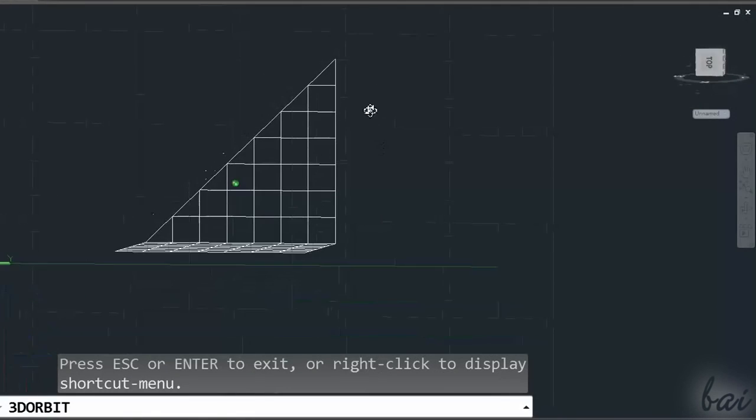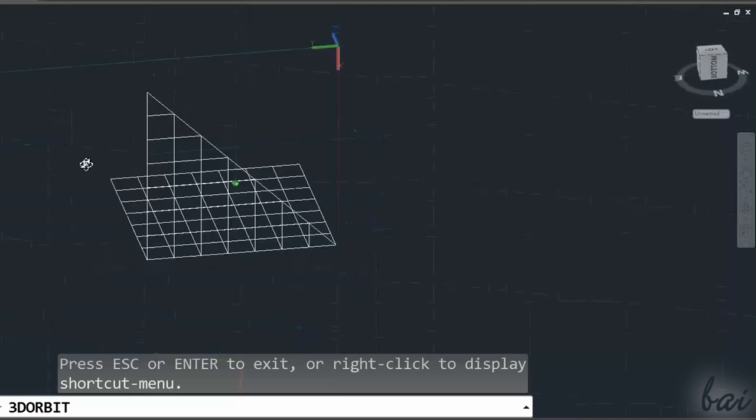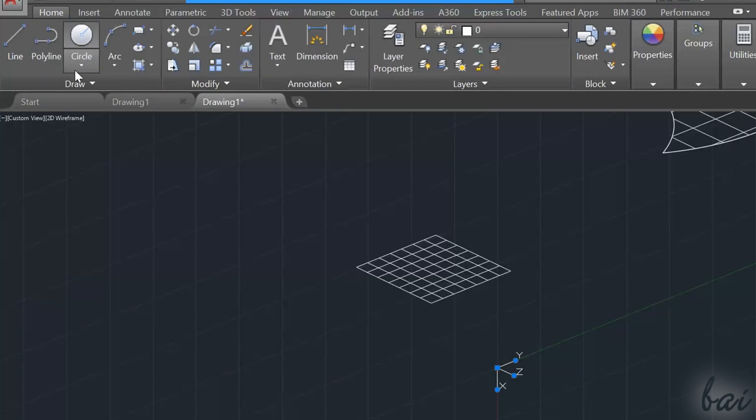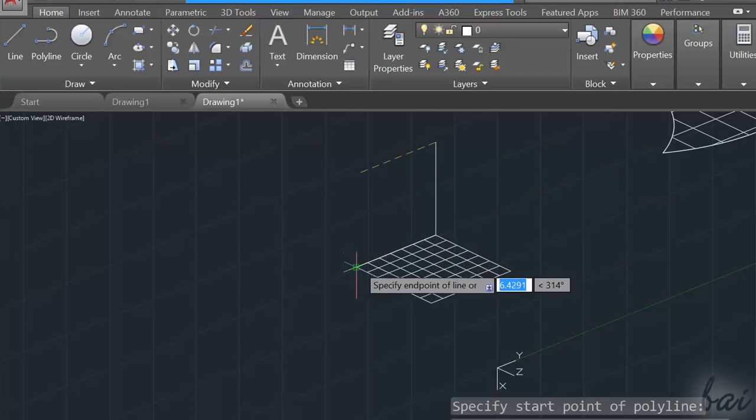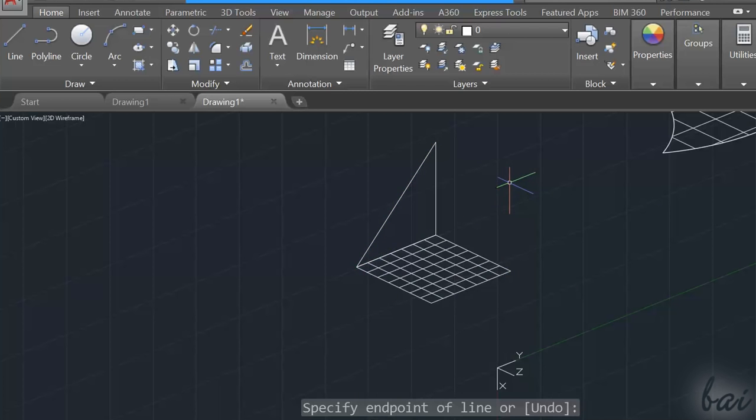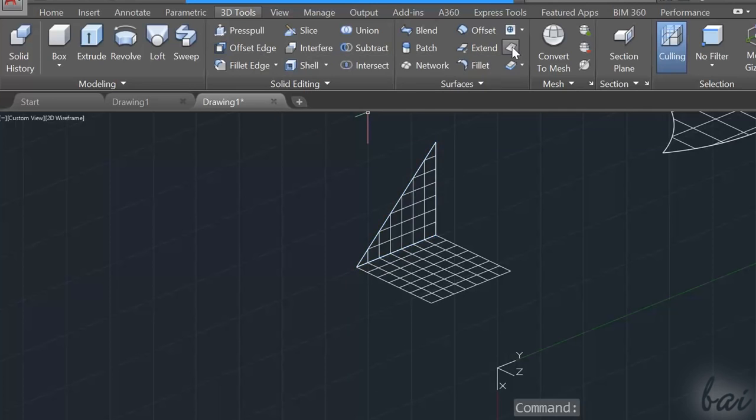You can also build non-planar surfaces inside your workspace. To draw a 2D boundary inside a 3D environment, you must use the 3D Polyline tool. Then, by exploding all the polyline sides, you can select each boundary to create the surfaces, creating an overall non-planar surface.